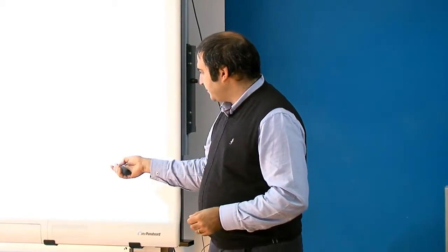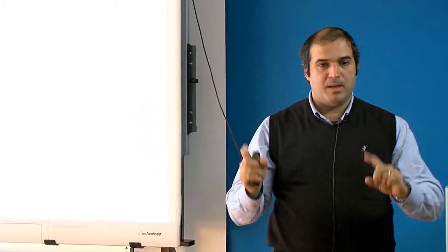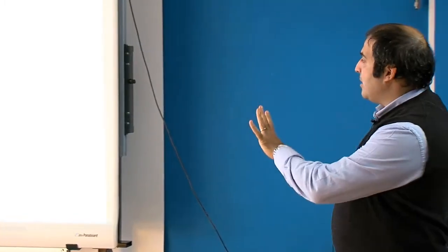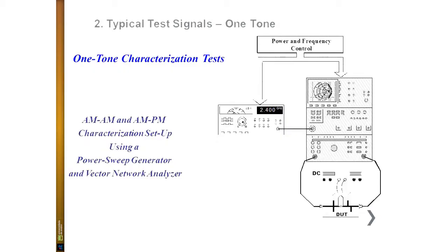And this is called AM/PM, which means that I change the amplitude modulation and I'm changing at the output the phase modulation. AM/PM conversion. Okay, so I can gather these values here, and how can I measure this? With a network analyzer. Network analysis is very easy to do. I have a generator, I have my device under test here, I put an input signal, output signal, and if I measure the frequency, I measure the linear behavior, let's say. If I measure the amplitude, I measure those values that I show you.